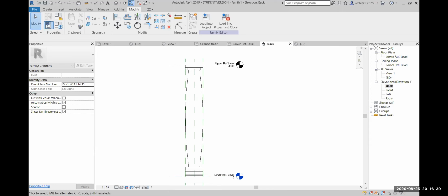Are you getting my point? Ma'am, I'm getting it, but I am thinking how to do it. That's what you'll have, because basically when you're doing the conceptual mass, you will have to sit with these tools, like creating different work planes first, making the leaf which is at the back. That can be done very easily. That will be easy to create. But the front portion, the one which is bending, that will be a bit difficult. That again you will have to create another portion of it and place it together.